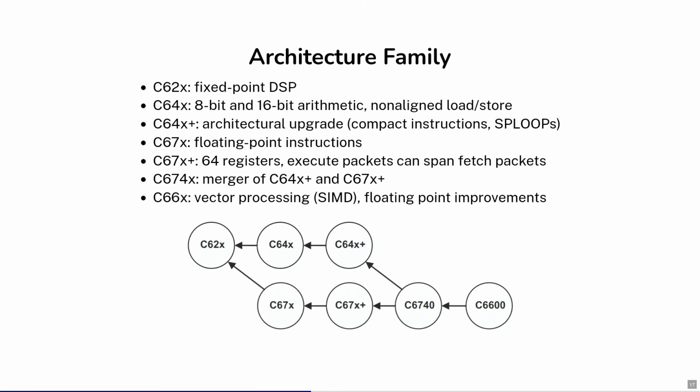And for example, the 64X versions are also fixed point DSPs, but they add more 8 and 16-bit arithmetics, non-aligned load stores. And one feature we will look at more in detail is compact instructions and software pipeline loops, because they also pose problems.